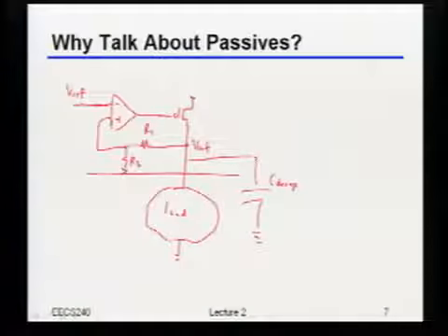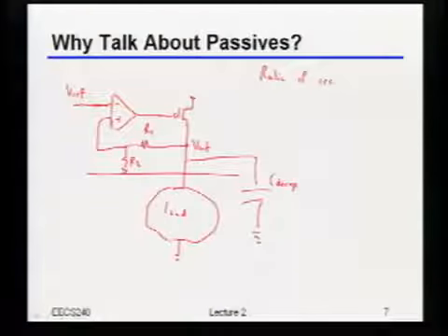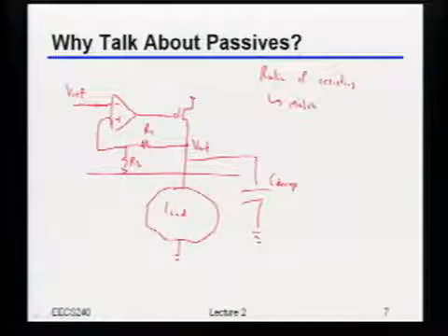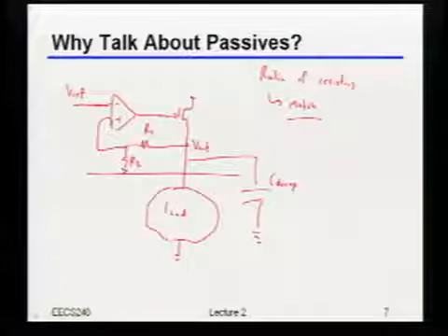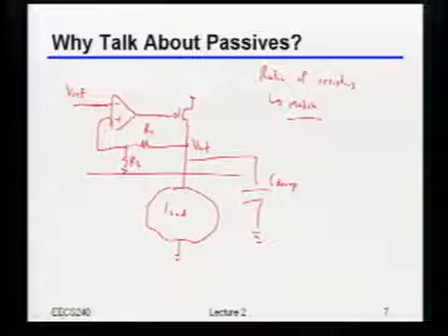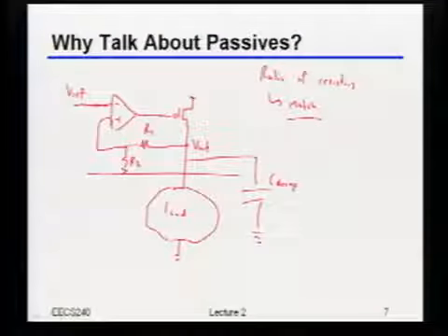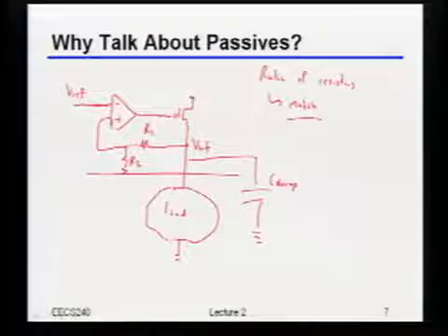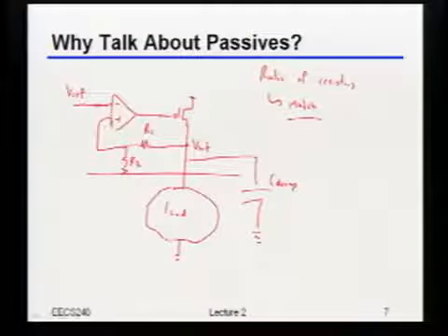The ratio between the two resistors. Yeah, it's the ratio of the resistors that sets the gain. That basically means you really want resistors that match. Okay, very good. That's one thing that we're going to spend a lot of time talking about. What else might you want from those resistors in this exact context? You're choosing the values of these things. How would you choose, or roughly what would you want to set those values to?